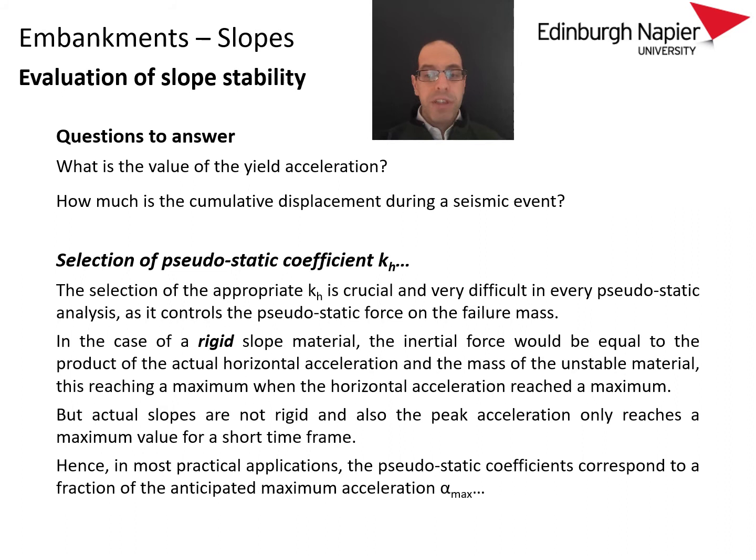So hopefully you understand the principle, but that always leaves more difficult questions. The first one, of course, is what is the value of the yield acceleration? And then what is the amount of cumulative displacement during a seismic event? The selection of KH, which will provide your yield acceleration, is crucial and is actually very difficult.